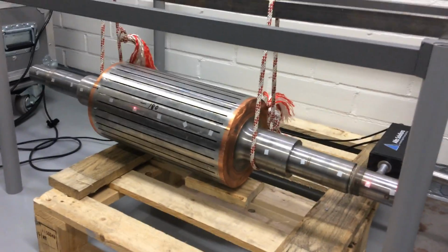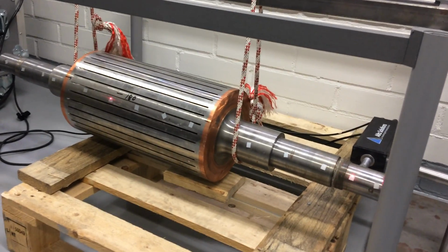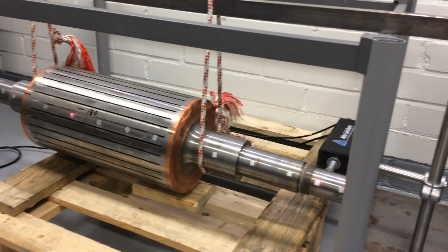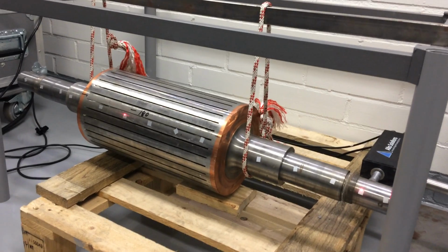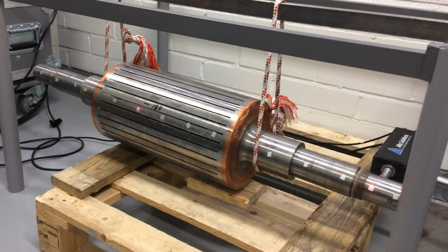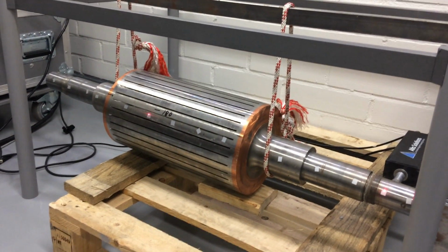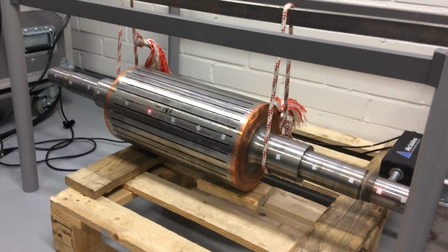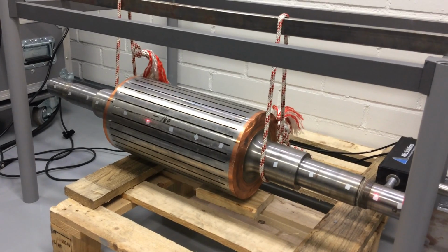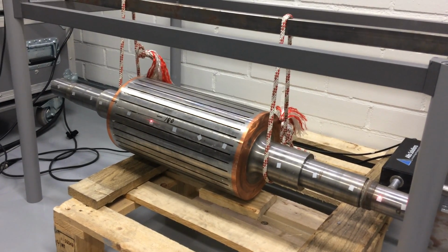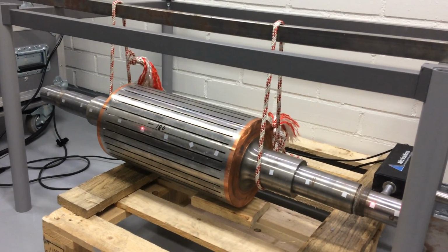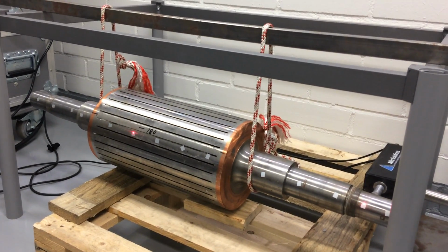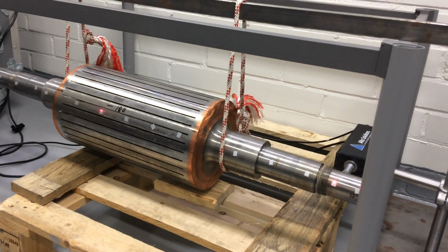So first, when it starts, we apply the force, for example with this automatic hammer. The laser, based on the Doppler effect, tries to read all those movements on the shaft, and later on generates the natural frequencies of the whole shaft. Okay.